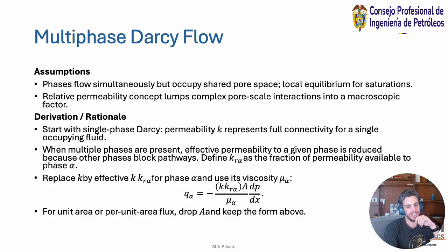And the main interpretation that you can take is that relative permeability is really essential when you're looking at multi-phase flow modeling, when you're looking at water flooding, right, because you're introducing a different fluid, and when you're looking at gas injection, because again, you're introducing a different fluid. And it also defines the fractional flows, the shock fronts, and recovery and efficiency, right?